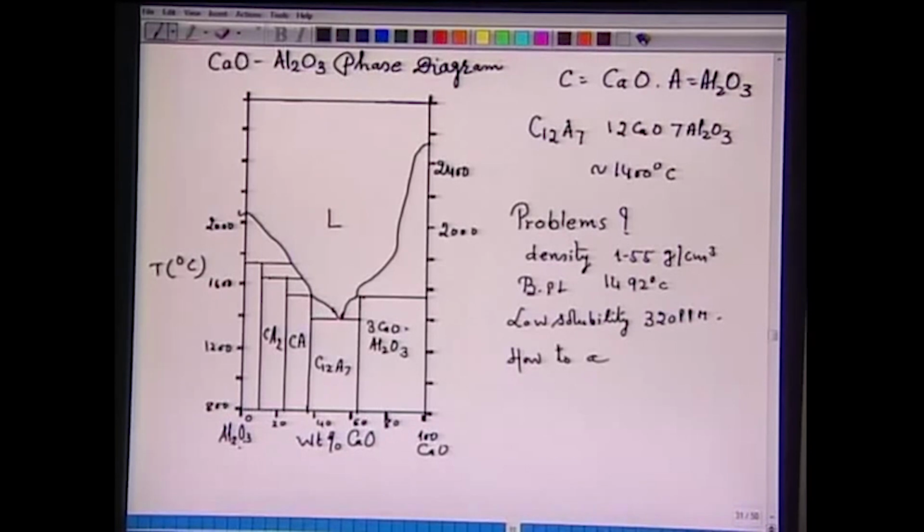How to add? It is added in the form of alloys: calcium silicide, calcium iron, calcium aluminum. Rather, it is added in a wire form, a cored wire in which calcium silicide is filled, and these wires are available in the form of a roll.